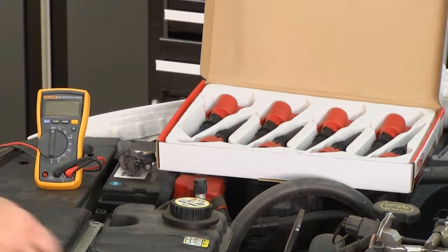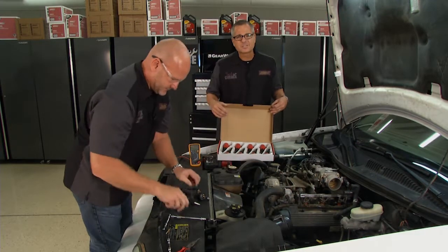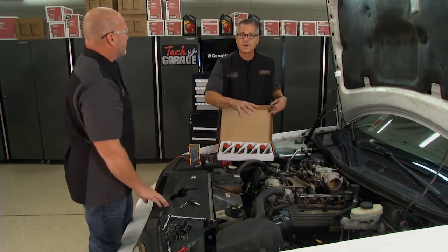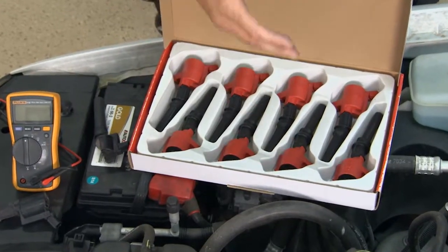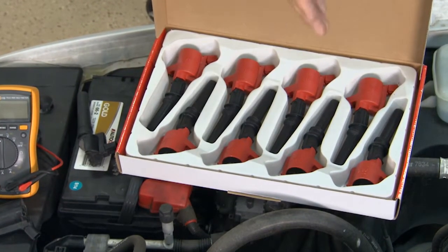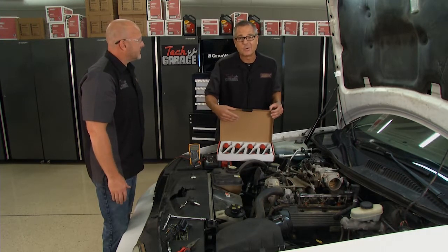Now, I know you're probably thinking, what do I want to do with 8 coils? One of them's misfiring. Well, logically, maybe it doesn't make sense, but here's the deal. You've got 8 coils on this car. Chain's only as strong as its weakest link. So what happens is you replace a coil, it's got 90,000 miles on it. It's just a matter of time. The other coils are going to start to fail. And as they fail, you're going to come back and think it's that coil. It's probably not. After 8 times, you're going to wish you would have got the whole set.